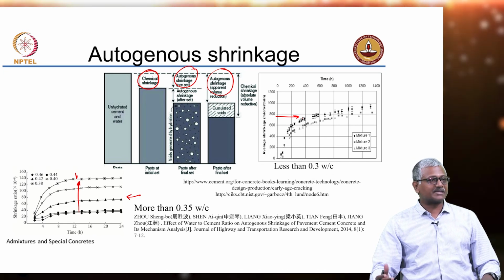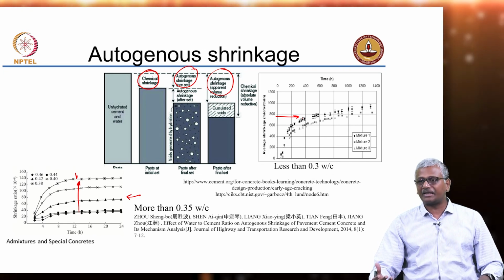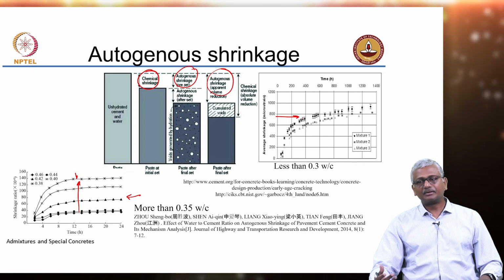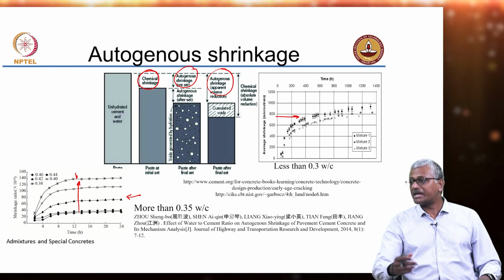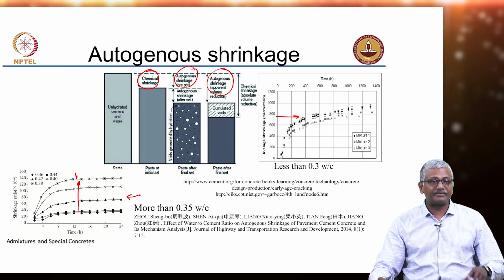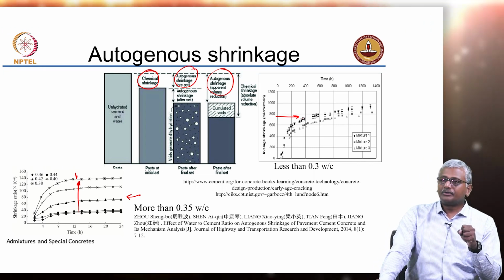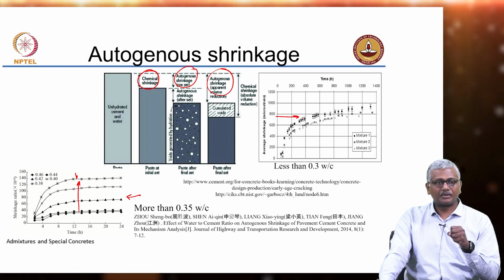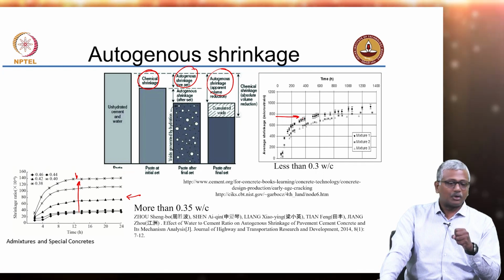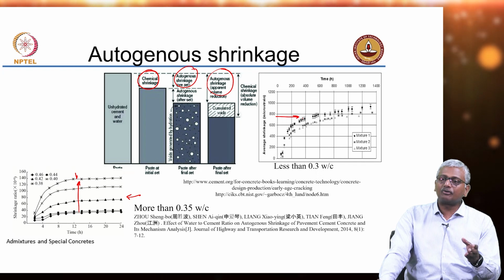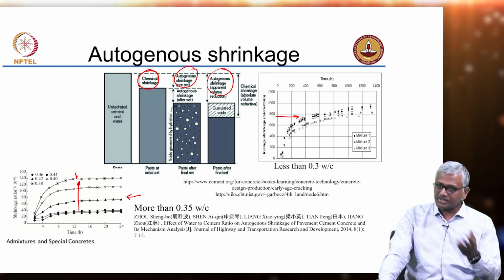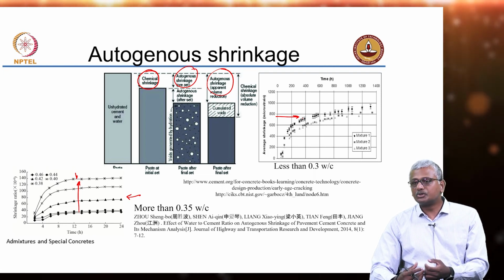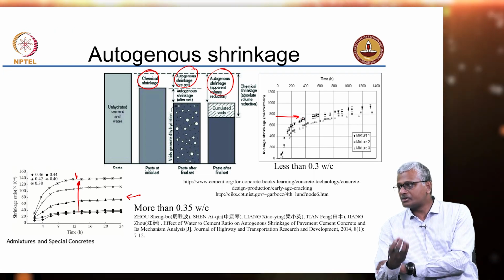That is why even when there is no tensile requirement, we provide minimum reinforcement to take care of temperature and shrinkage effects, right? We call it distribution steel. So, in such cases, when your concrete is bound to have higher shrinkage strains, your provision of steel also has to increase. Now, inevitably, the problems leading to cracking of high strength concrete is not just because of shrinkage, it could be also because of thermal effects. So, all your steel that you provide should be also looking into shrinkage and thermal effects.